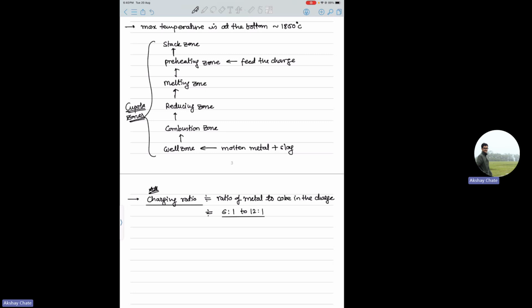So the refractory lining, which is inside the furnace wall, sometimes gets damaged pretty easily or more frequently, because even refractory materials have some working life, and therefore sometimes they are water cooled also. The refractory walls of the furnace, that is called a water cooled cupola. Okay, and sometimes, depending on the nature, the pH values inside the furnace, if it is acidic, you have to put some basic linings on the refractory and vice versa.